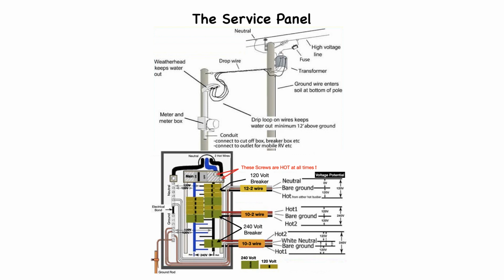The overhead power connection from the utility lines to the service entrance is referred to as the service drop. It has 3 wires: 1 neutral line, and 2 hot lines. The hot lines maintain a certain potential like 120 volts with respect to the neutral line. There are 2 types of service connections, an overhead mast service drop, or an underground service connection.